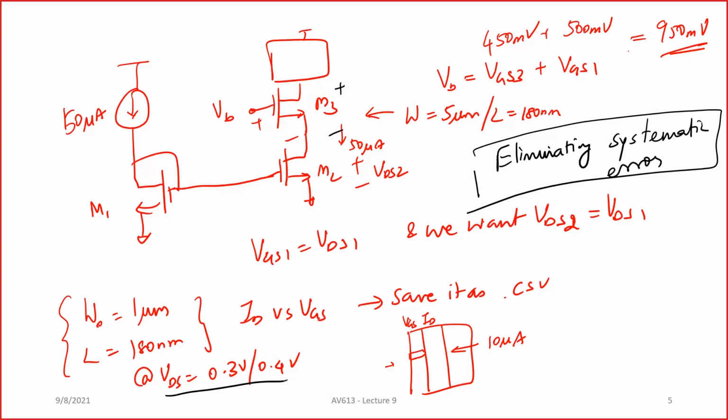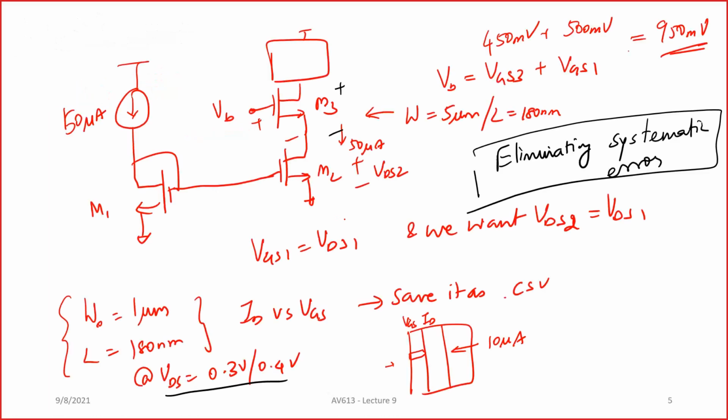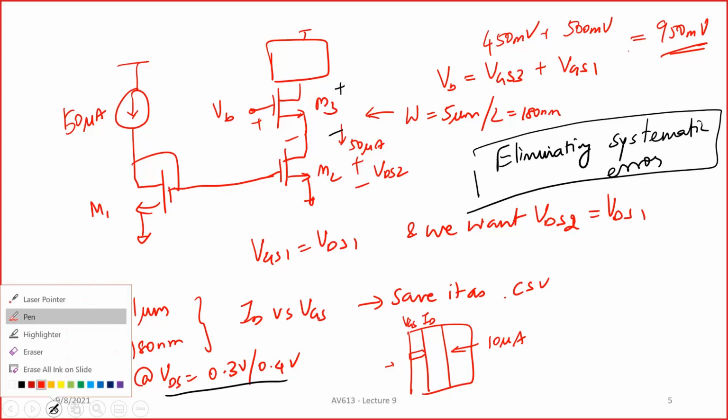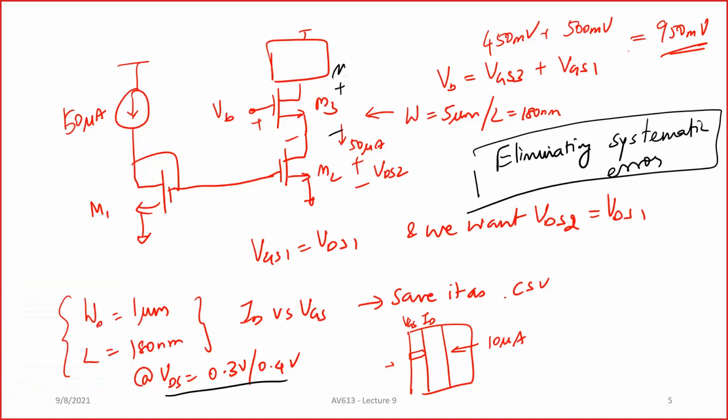Okay, sir. Now, how to calculate the output impedance? So first of all, let's look at the R out of a single transistor. What we do here is go to the small signal analysis. Why small signal analysis? Much of this output impedance stuff is important because there will be some kind of signal swing happening at this particular node.